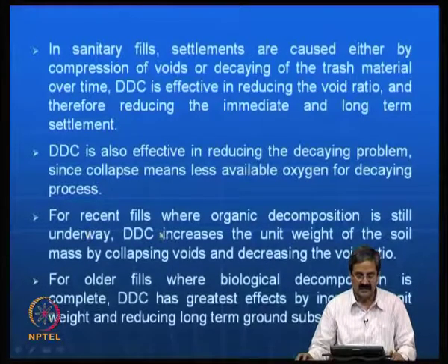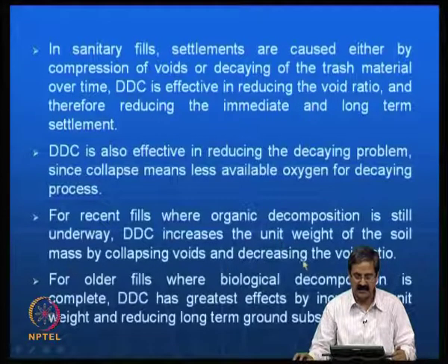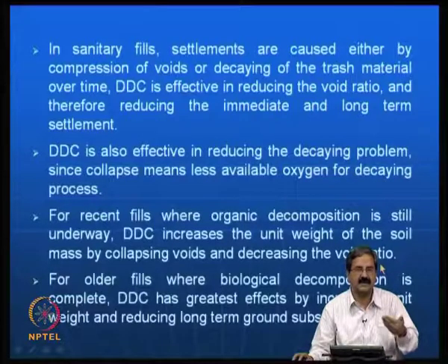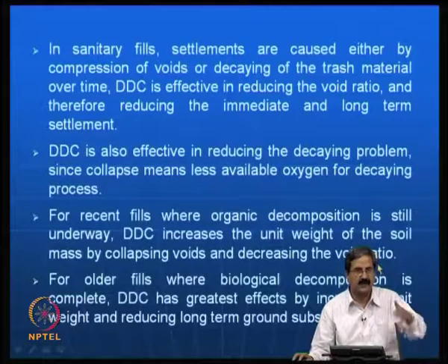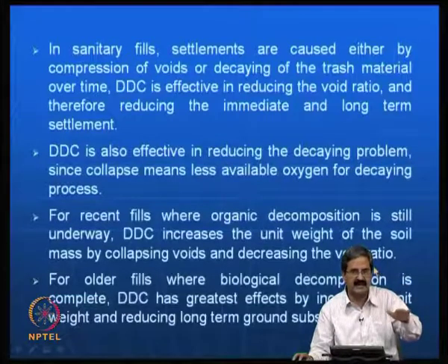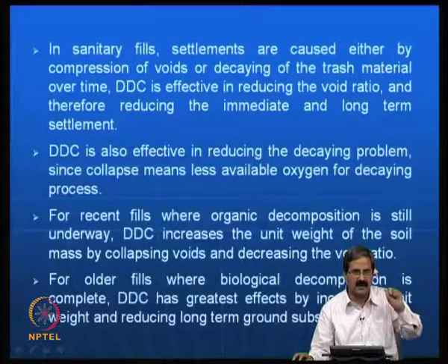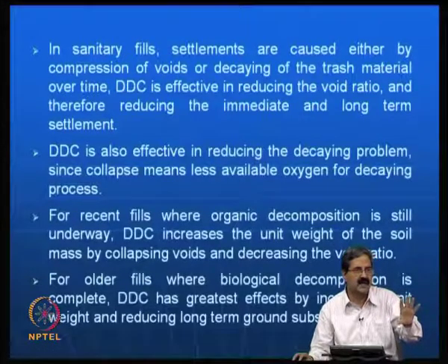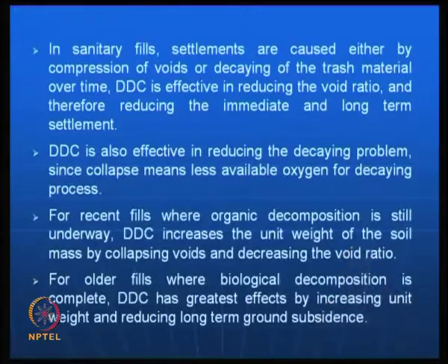Then for some recent fills where organic decomposition is still underway, dynamic compaction increases the unit weight of the soil mass by collapsing voids and decreasing the void ratio. Actually, it accelerates many things. What it is trying to do is accelerate much of the settlement. Say, for example, if the biodegradation takes 5 years, and if I just do the dynamic compaction, all the voids are reduced and the settlements are preempted.